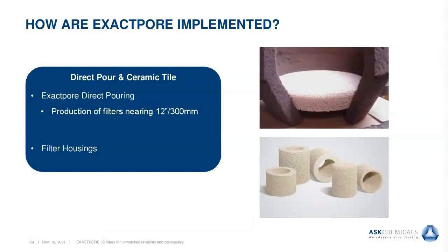This tapered filter is placed in a neck down riser where the metal will be poured into the filter, allowing the oxides to be removed and modification of the metal into the casting cavity. Once full, the filter will be allowed to float, and that will maximize the cross-sectional area of the riser with the casting and provide efficient feeding.